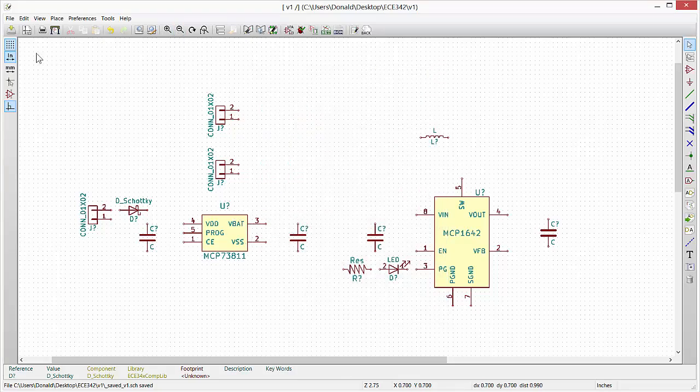From there, since I actually had the original grid, everything's already set in place. Otherwise, I would bump everything to make sure it's lined up properly. So we'll wire up this first little bit just to see an example of how this wiring can go. It's also pretty important to do this because the endpoints of where the parts are made, as long as they're on the same 50 mil grid as everything else, allow us to quickly connect rather than having to zoom in great detail to make those connections. All right, I'll keep getting it wired.